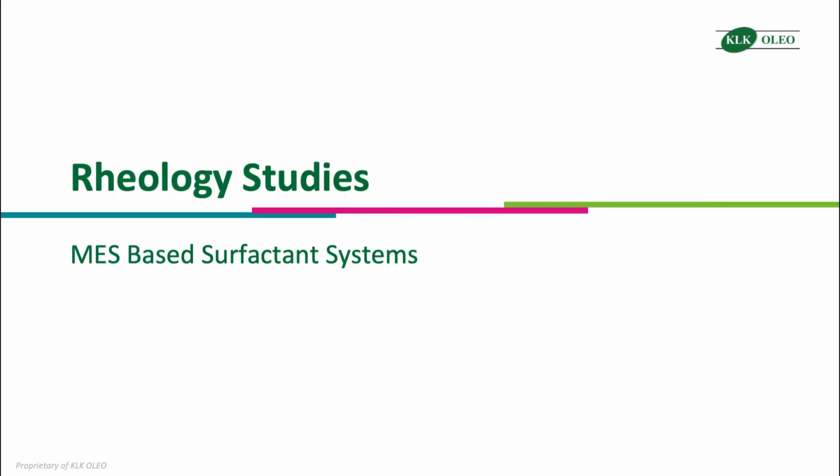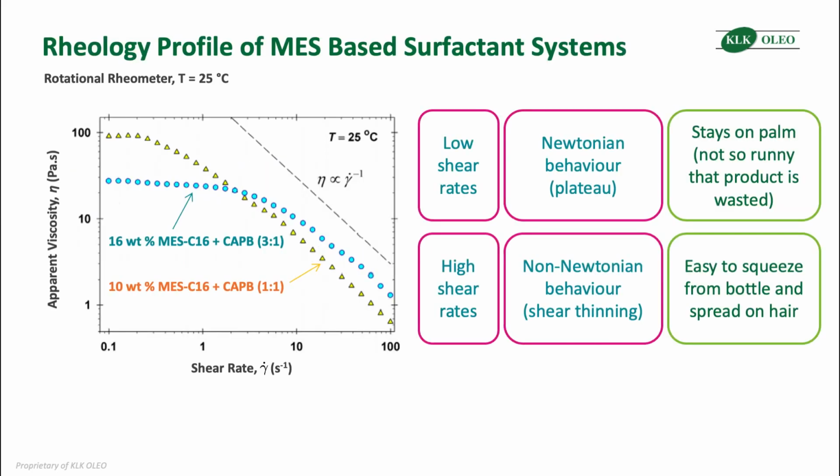Our second topic for today's presentation is rheology. While oil drop deposition is important for delivering more conditioning effect, the rheology profile of a shampoo is important because it's linked with consumer sensory evaluation. For example, how it feels on the palm and how easy it is to spread across the hair. Different formulators may desire shampoos with different rheology profiles. The aim of our next study is to evaluate how easy it is to modify the rheology profile of MES-based surfactant systems.